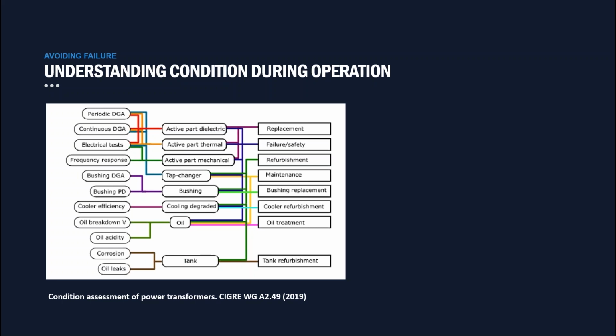Very high levels of acid can corrode metal parts in a transformer, and sludge, which comes from oxidation of the oil, can also block up the cooling fins and reduce the efficiency of the cooling system. This can lead to overheating. Acidic oil can also degrade the paper insulation directly. The consequences can be a requirement for oil treatment or premature replacement of the transformer if the paper insulation reaches end of life.